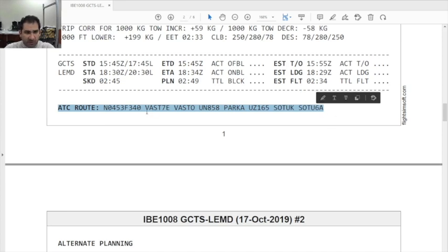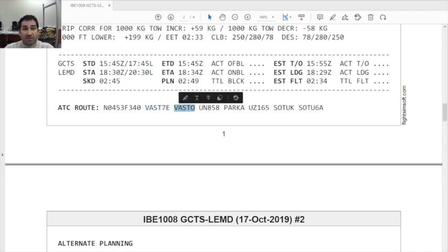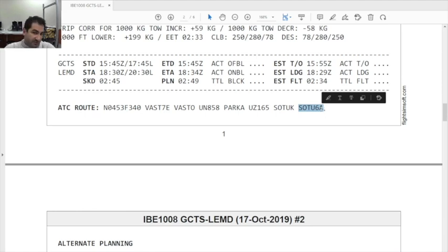You have a kind of seed, right, a waypoint already in the route, then an airway, another waypoint, airway, waypoint, and then the start arrival. You will need to select, of course, the ILS, and this is supposed to be consistent with the operational runways in use in the airport, right? But if this is not the case, you should be able to change your route accordingly.